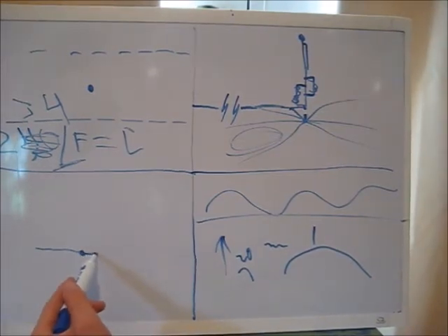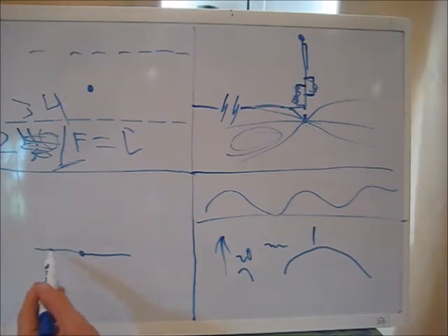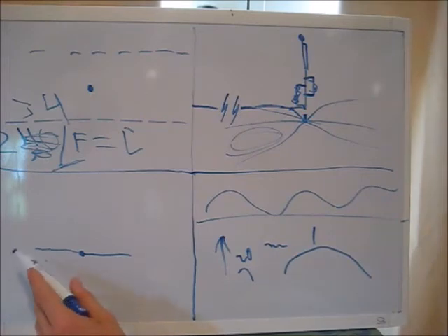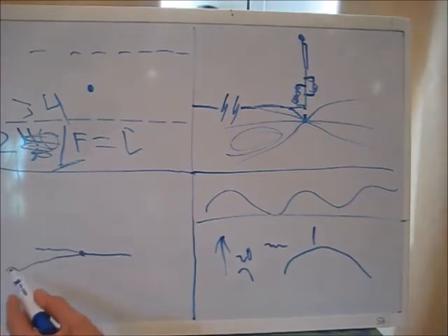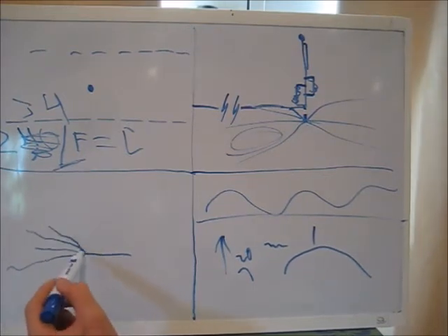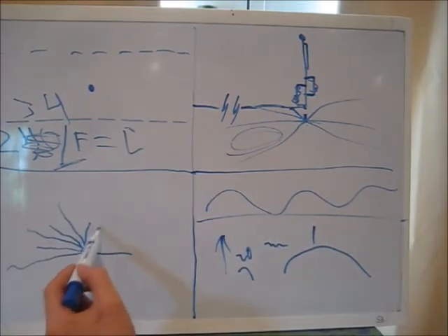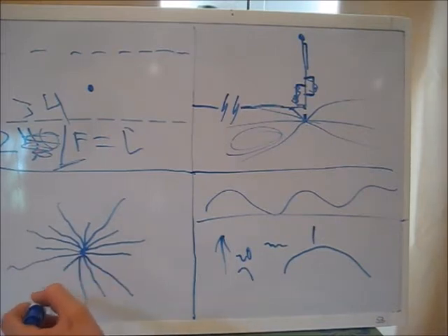So ideally you want as many radials as possible. And assuming you buy a vertical instead of build one, you'll probably get a 2-bander version. So the best way to put your radials in is about 1/2 inch in the ground. Just bury them a little bit so you're not going to mow over them, and offset them. So if you've got a 2-band version, say one for 20 meters and one for 10 meters, your 20 meter radial is longer, so go 20, 10, 20, 10, 20, 10, etc., etc. You can keep doing this as much as you want.